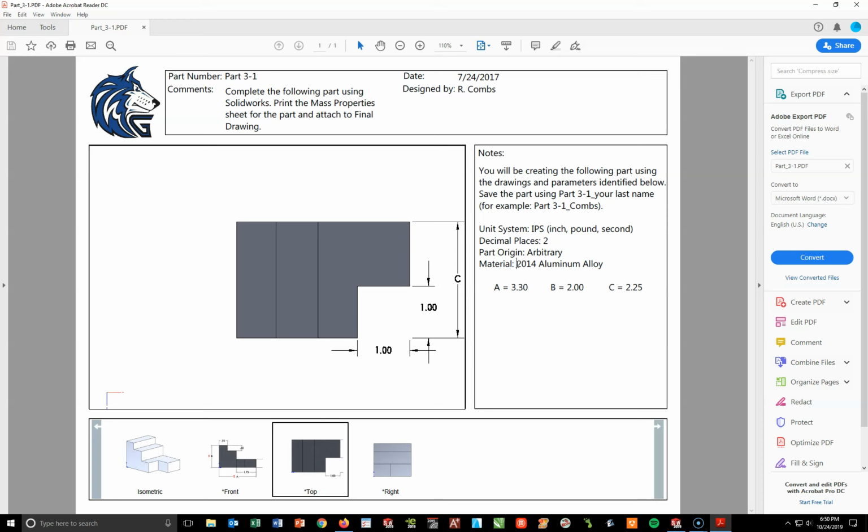As you can see, we have a pretty extensive list of materials that we can use. There's a ton of steels, tons of irons, aluminum alloys, copper alloys, and you can continue thumbing through and see there's all kinds of materials we can add to this. Now, we were told in our directions to add a 2014 aluminum alloy. So I'm going to drop this arrowhead down, and right in numerical order, coming down the list, I see a 2014 alloy. To get the material to add on, you left click on the alloy.